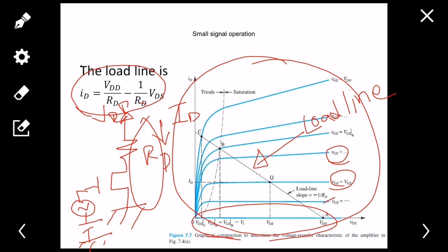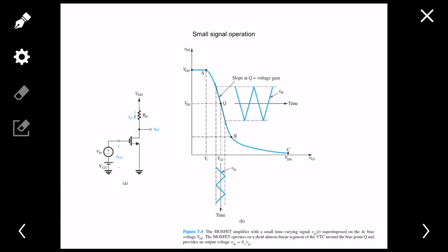Right now I'm giving the AC input at the gate. I'll be measuring the output at drain to source. So consider my input is gate, and my output is drain. Now if I use this particular curve and draw the input versus output voltage curve, that is known as the voltage transfer characteristic curve, it will be something like this. So my x-axis becomes VGS and my y-axis becomes my output, that is VDS.